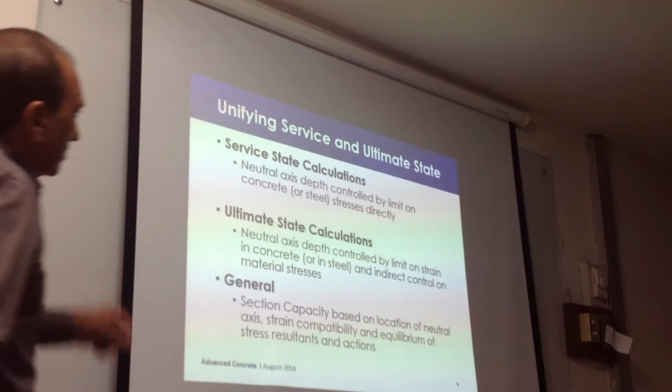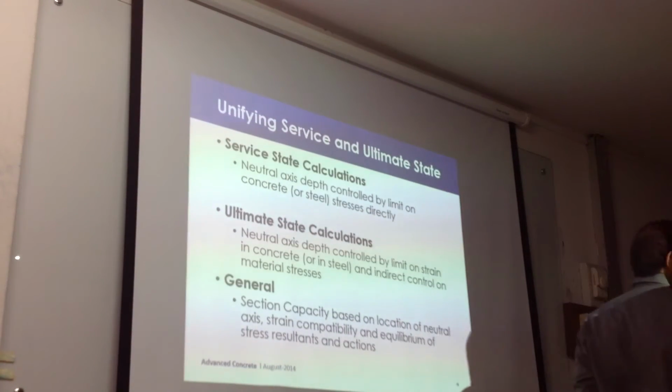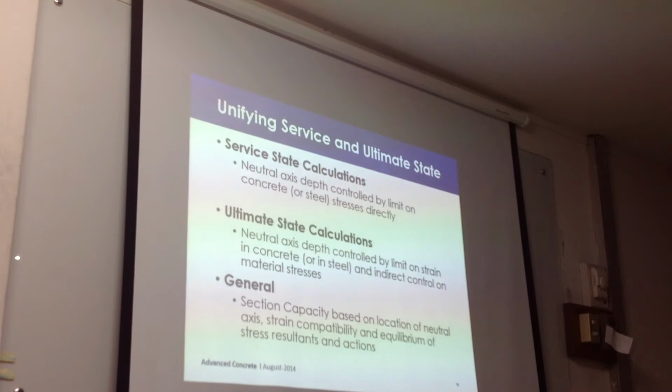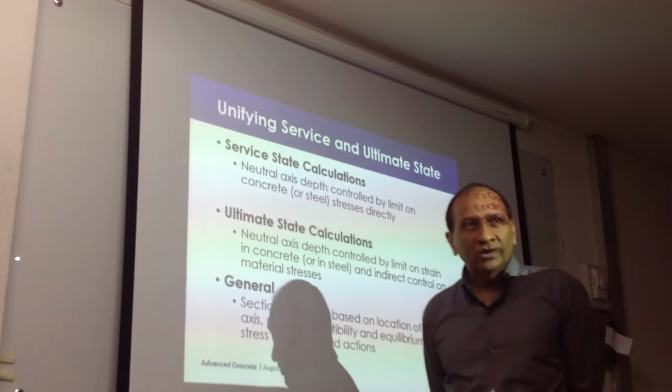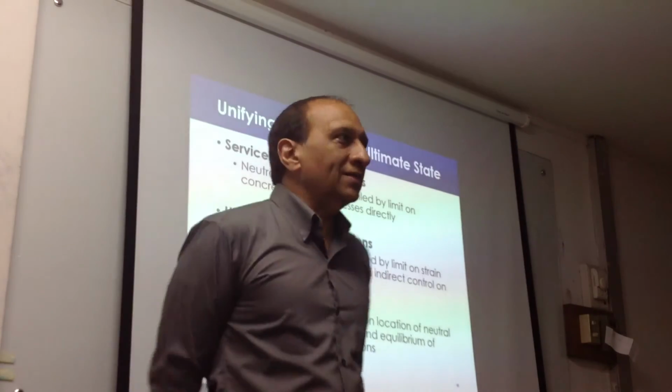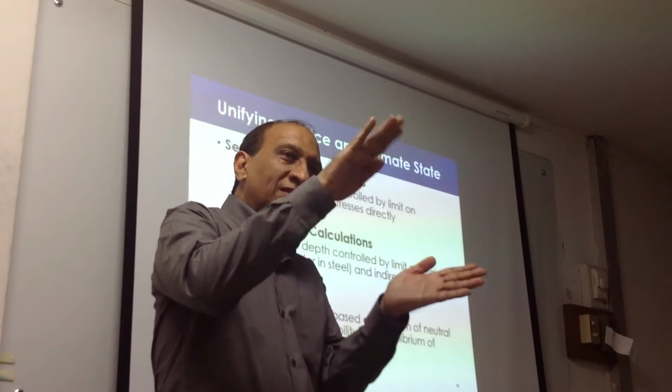So, what is the difference between various limit states? Let's come to that now. Various limit states simply use a different level of stress or strain on the stress strain curve. That is all they are. They limit the stress or strain value for a certain purpose on the stress strain curve. They are still on the stress strain curve or the load deformation curve. To control cracking, they say limit the crack width. Everything is controlled, so you are within a certain strain.